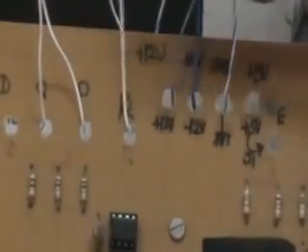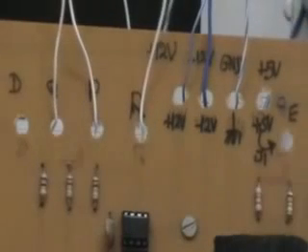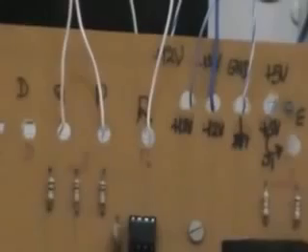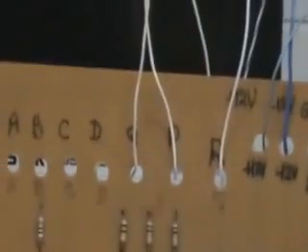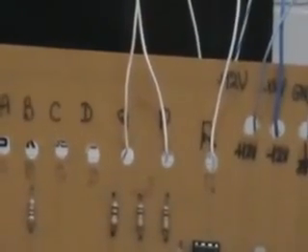If you give two inputs to Q and P, the output will be the difference of voltages across Q and P. So it is given in the manual that VR is equal to VQ minus VP. So you should not forget connecting the plus 12 volts, minus 12 volts and ground connections in the PCB.